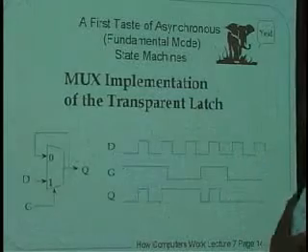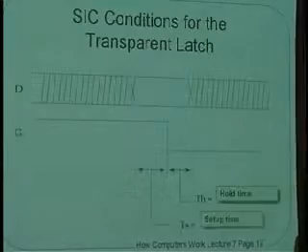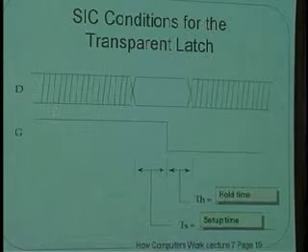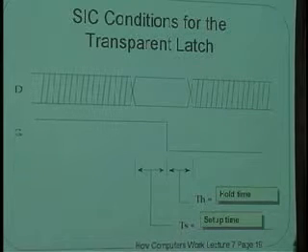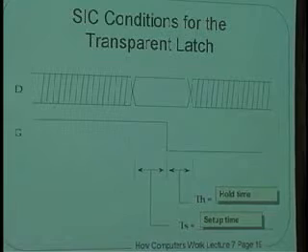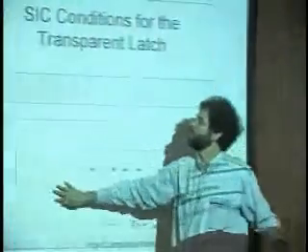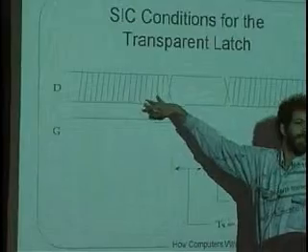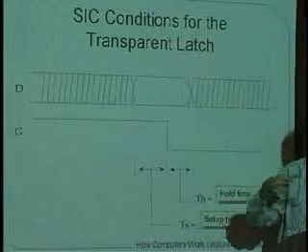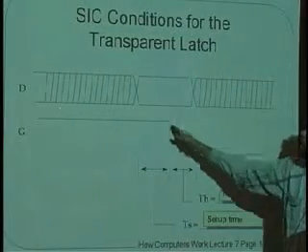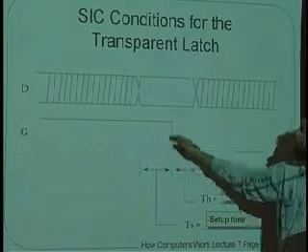And it turns out that that sort of limitation, saying only one input change at a time, is exactly the same as the thing we talked about in the last lecture, saying that there should be a setup time and there should be a hold time around the instant that a memory element needs to capture whether an input is a 0 or a 1. It's the same as saying that when you take a picture, you want the person to hold still. So when the gate is high, the output is going to follow the input data, whatever it is, 0 or 1. Doesn't matter. However, we know that we want the gate to snap closed and for us to go into the feedback mode and latch on to either a 1 or a 0. Around that time, let's make sure that the data doesn't change.